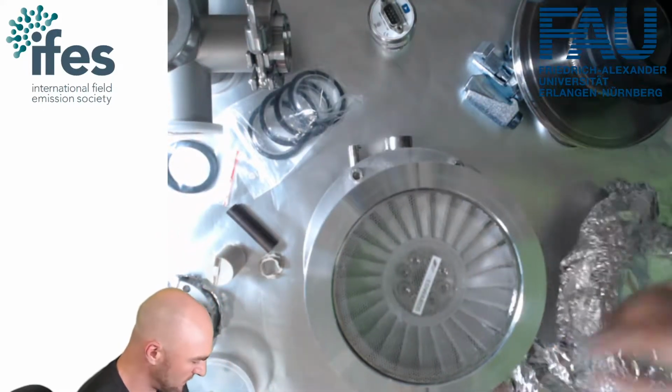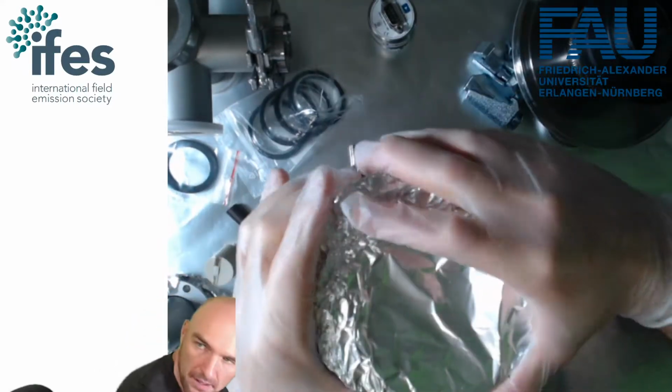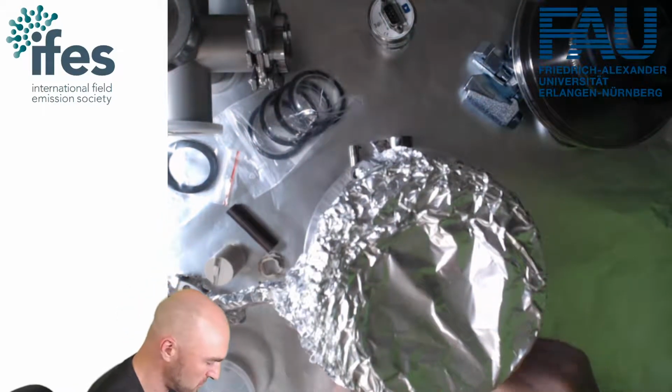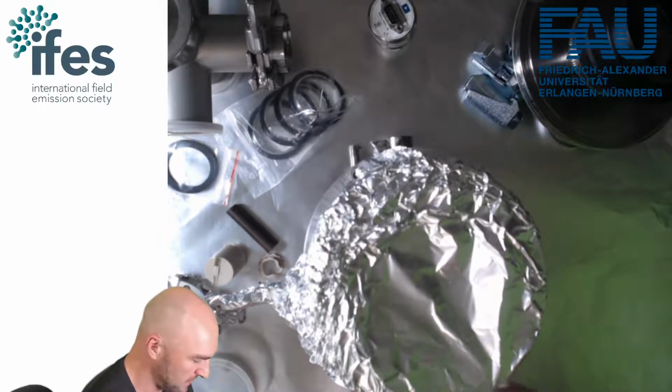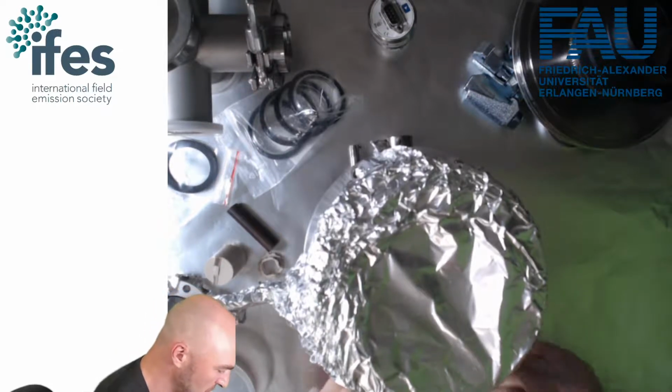So if you want to run down a turbo pump, it can take quite a while until the turbo pump actually spins down. If you have a good vacuum and you just let it spin down, it might take something like 15 minutes, which if you're operating an SEM or an atom probe with a load lock, you don't want to wait for every single time you want to open the load lock.